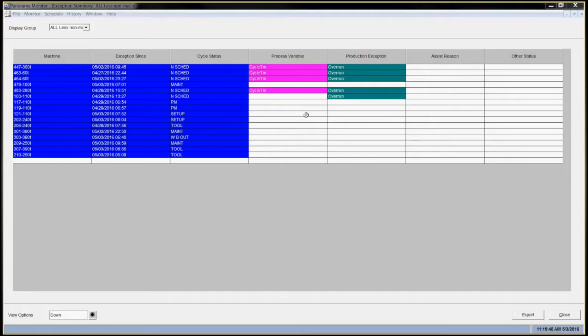During my day on the floor, I can sit in my office and look at my screen and see exactly what we have down in the shop. This screen here, you see I have 3 down for tool, not having a great day. I have 2 down for mold PMs. That's something else that we can do with Plantstar. It tells us when we need to PM a tool, we pull it out, I get it, we clean it, grease it, and send it back.